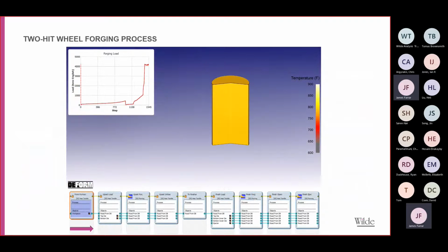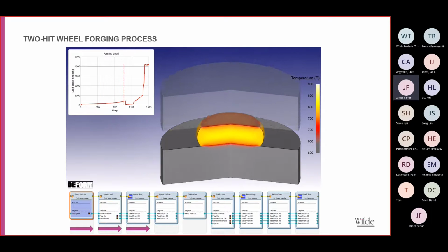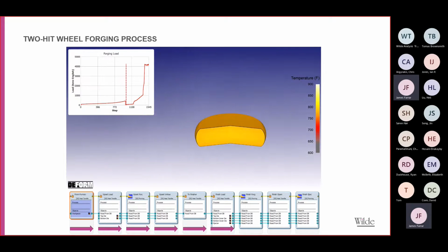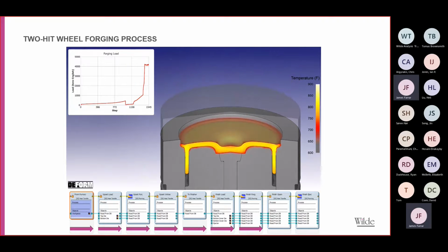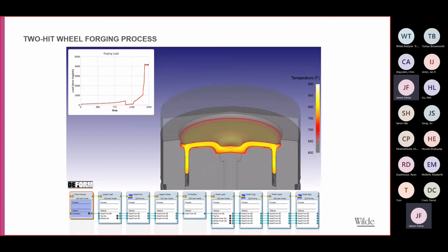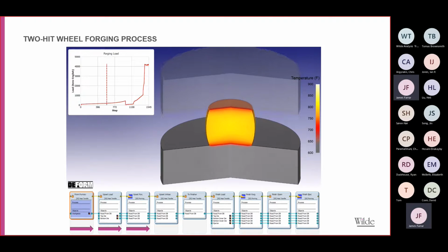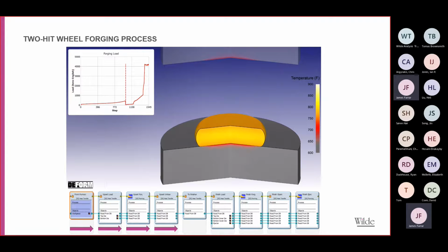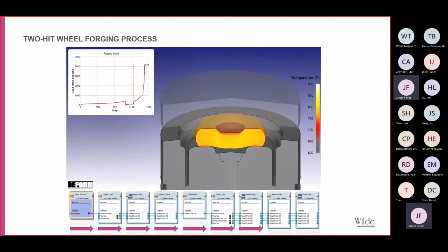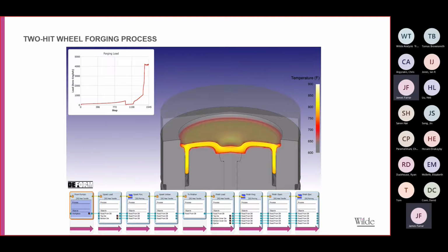So here we can see this in process. We have the initial heat up with the furnace, we transfer through the forging operation, it rests on the tool, we take it to a finishing operation, do the forging, open the tooling. It's a bit quick, that video, but I'll just run it again. So the DEFORM system allows us to set up these multiple operation applications so that we can delve in and modify each one separately. And once we have this set up as a process chain, we can save that as a template, so you can develop your own bespoke template for your particular operation.